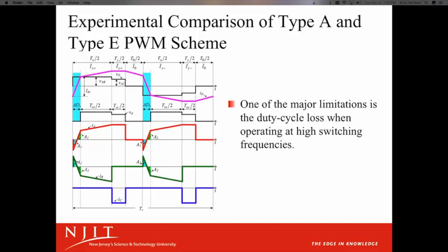The author states that the duty cycle loss, delta dx, happens at the transition from zero vectors to active vectors due to the finite transition time depending on the value of the inductance on the primary side. Since the input phase current is produced by the IP current on the primary side, and since the IP switching is swinging from one direction to another, the two phase currents IA and IB contain two triangles, A1 and A2.